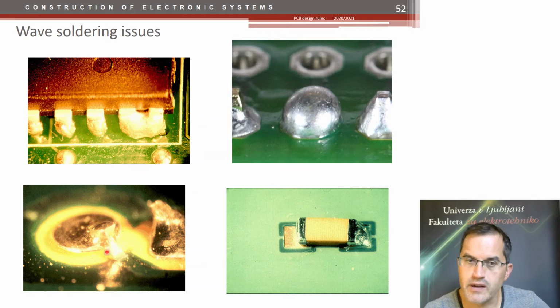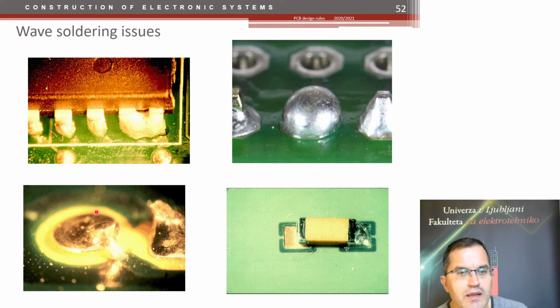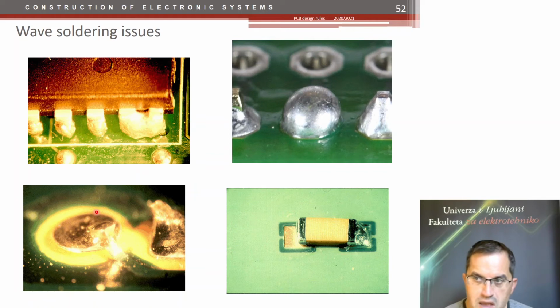And the copper can be lifted off. This happens mostly on a single-sided PCB where holes are not metallized, they are not supported, and they can easily be peeled off. So on single-sided PCBs, you should use thicker copper layers and larger pads so that more area is attached to the PCB.